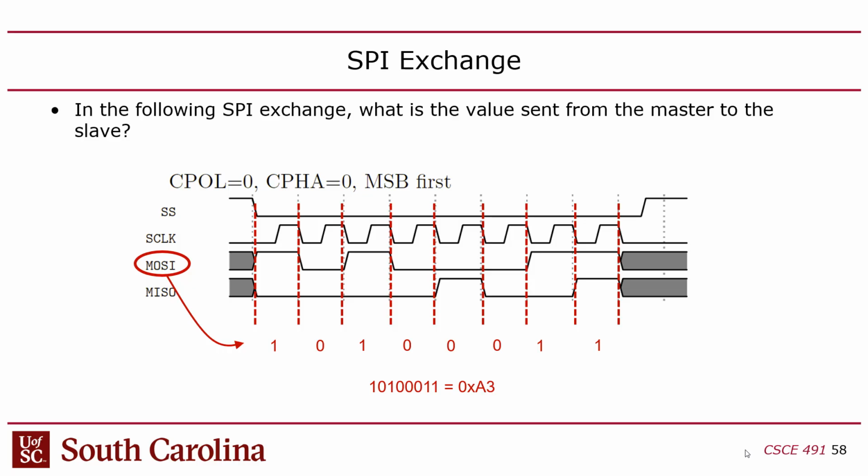Yes. Okay. But again, like I said, I just want to reinforce this point. The whole point of this is that you're trying to get the signal stable. You want to have a setup and hold time. You don't want to violate the setup and hold constraints. Right? The setup says you got to have it stable before the edge. The hold says you got to have it stable after the edge. I don't know what the setup and hold time is because it's technology dependent. But if you follow these rules, you're going to get the best. It's optimized, right, for that, right? Okay.